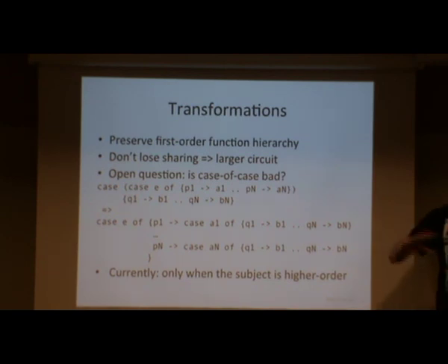Now something about the design, the decisions about the compiler itself. I told you in the beginning, when hardware designers design hardware, and also in my PWC group, they always think of this schematic. When they push the synthesis play button, they want to see the RTL diagram, and they want to see this schematic again. Only then do they believe that everything worked out all right. So it's very important to preserve the first order hierarchy of your function hierarchy.